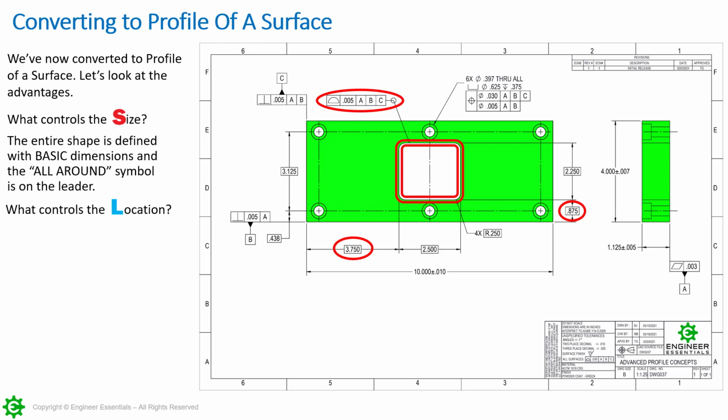And what I mean is we can now put this on a granite table. Once we have all of our information here, we know what the requirements are. It's easy to put this on a granite table and use a height gauge, whether it be a flat blade or you have a dial indicator stuck on the end of it. You're obviously going to have to calibrate that and zero it out. But once you do all of that, it's easy to take these measurements.